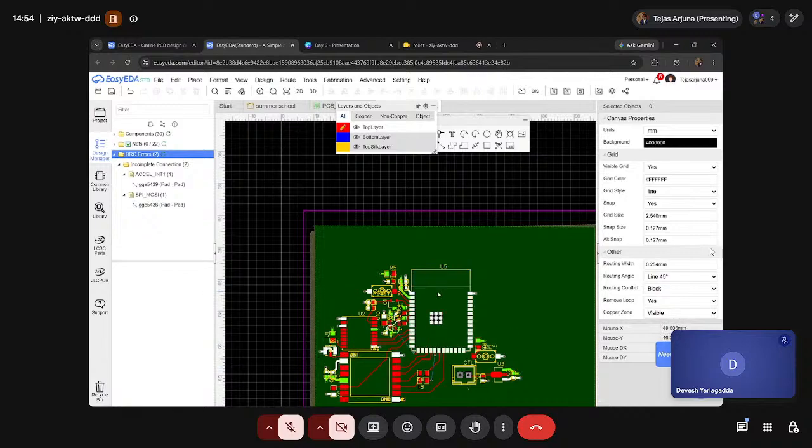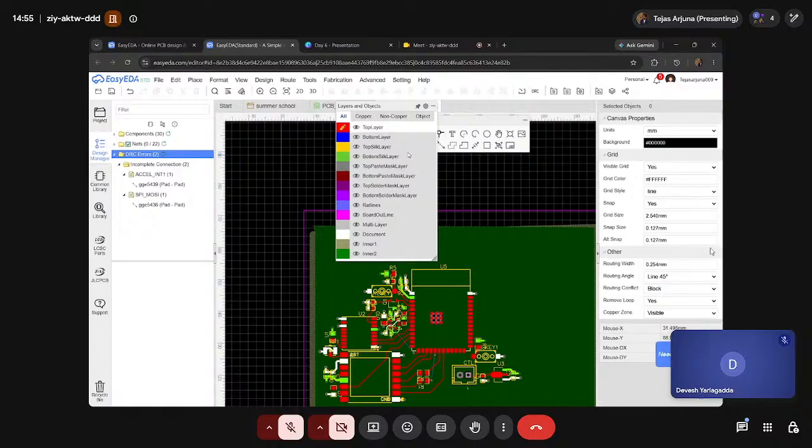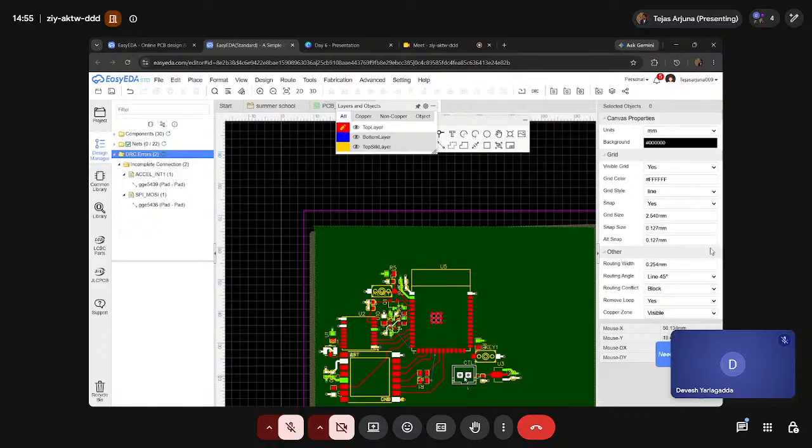If we have large loop areas, EMI interference is prone to occur at a high rate. We want to minimize everything because we are using LoRa. It's a weak signal, though it goes for a long distance. We go to the bottom layer and do the connection. That's it. We are done.